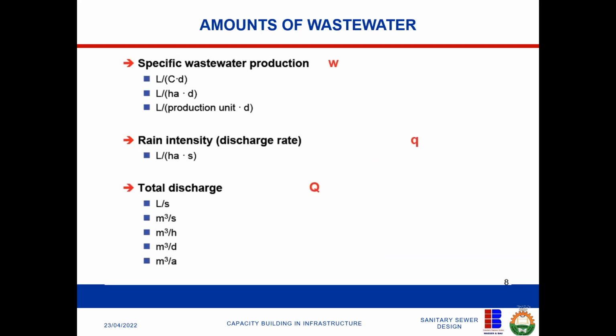So specific wastewater demand, for instance, we talk about the liter per capita per day, which is what we use in water. You use it again in wastewater. So that is how to rate your input parameter for your sewer design. As you want to design your sewer, just use the value you have used as your water intake. That's why in some countries, as they are charging you for drinking water, they are charging you for wastewater. The same thing. You pay for both. Why? Because they expect you to also produce what you have taken.